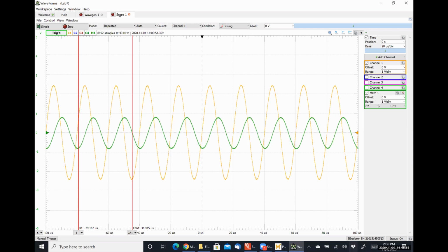So if omega increases, what happens to Z? It increases. All right. So we have increased the frequency from 17.5 kilohertz to 50 kilohertz, which means we have increased the impedance of our inductor. What happens when we increase the impedance of something? It's the same as increasing the resistance, right? So we should have observed that in our simple voltage divider circuit, because that's exactly what we have, it's a voltage divider circuit where we're using a resistor as one element and the inductor as the other. When we increase the impedance, the voltage drop over the inductor should go up and the current flowing through the inductor should go down because it's just the same as if we increased the resistance, right?